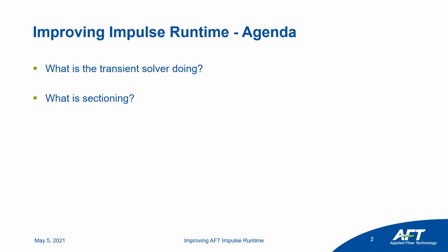So it's one of the 5 essential steps in creating an impulse model. One of them is sectioning your pipes. Usually that'll be sectioned for you, and it might not be a particularly difficult choice of how many sections to include. But by understanding what sectioning is, we can also see how that'll impact our runtime, which in this case, we're trying to optimize.